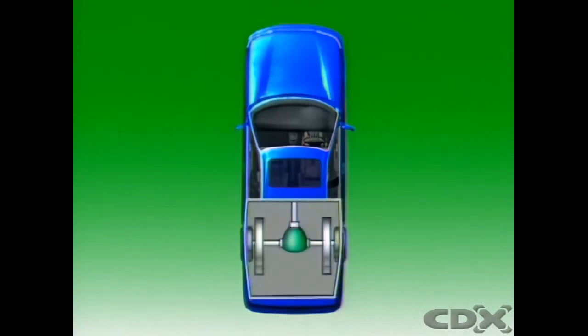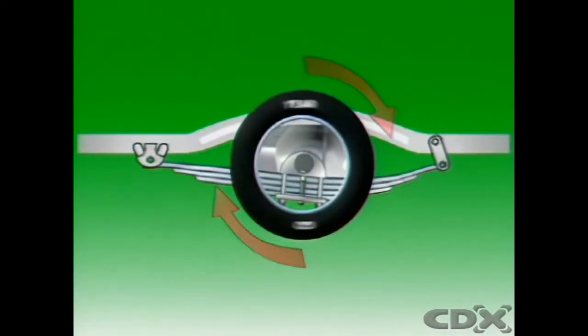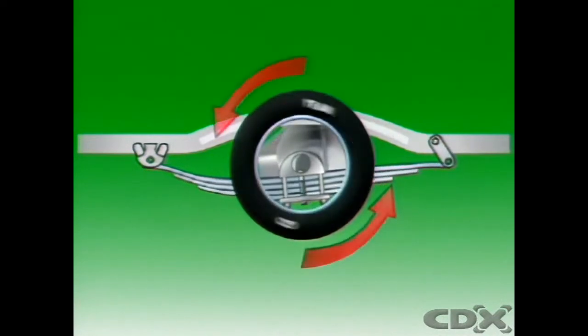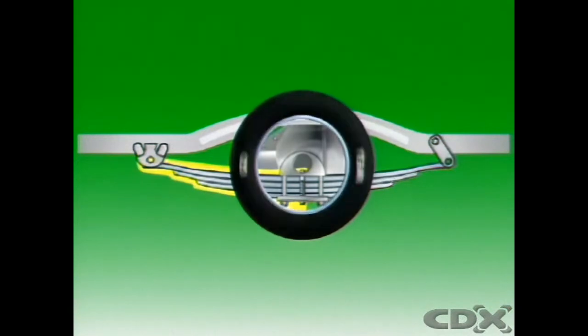The spring forms a flexible suspension unit that locates the axle housing longitudinally and laterally. It can sustain the torque reaction on acceleration and the braking torque during deceleration, and the driving thrust is transferred through the front half of the spring to the fixed shackle point.